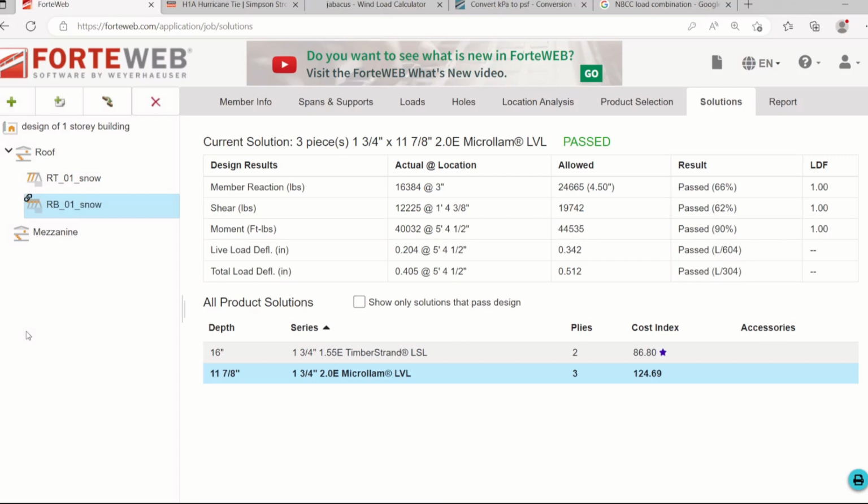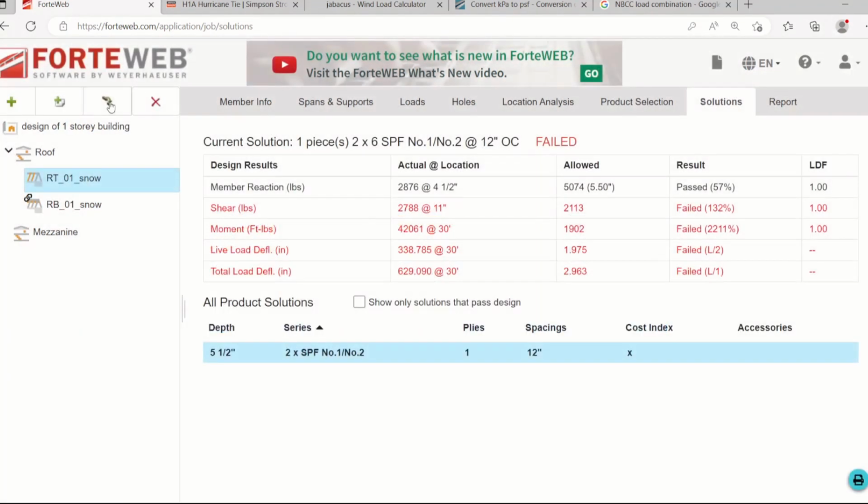And then if the funding load governs in the overall design, then you will use the funding load for the truss, like the design for all the structural elements. So roof truss 01. So we will copy this one. So this one, copy member. Like I said, you can use this one since we have the same truss. The difference is only the load. So we don't have to update all the load, the span again, the bearing again, right?